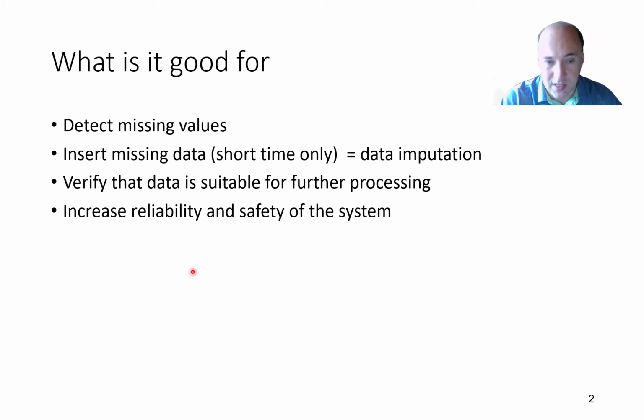So for example, again, let me use the temperature example. We measure a temperature in a room. We know that it should be somewhere around 20 centigrades, and we get an uncertainty of our data of, let's say, plus minus 1 centigrade. Then we may find that this is okay. We will be fine with measuring 20 centigrades plus minus 1. But then something goes wrong with the sensor, or you may have some interference in your signal, and suddenly your uncertainty will increase. So you will still have the 20 centigrades, but now it will be plus minus 10 centigrades, or plus minus 20. And then, based on this uncertainty, you may tell that there's some problem, and that you probably will stop the process, or make some warning, or discard the data completely, because if you measure 20 centigrades with plus minus 20 centigrades uncertainty, then certainly this is wrong.